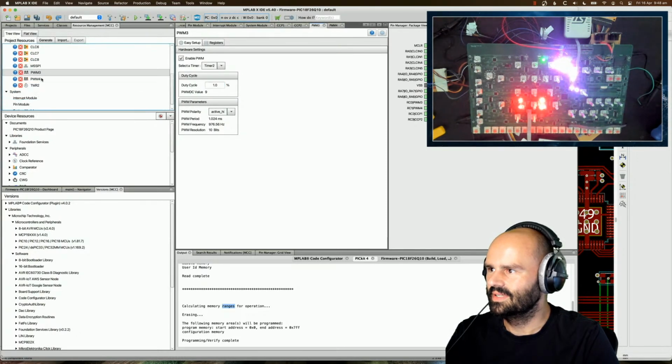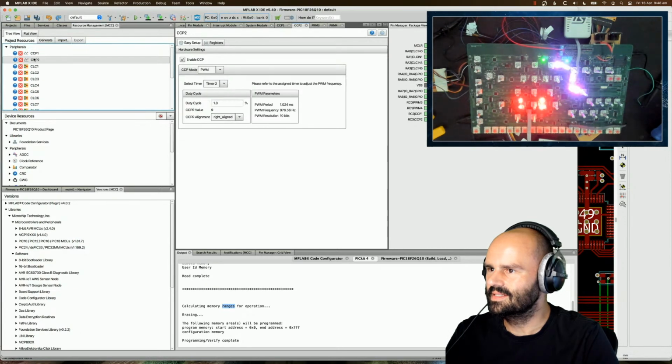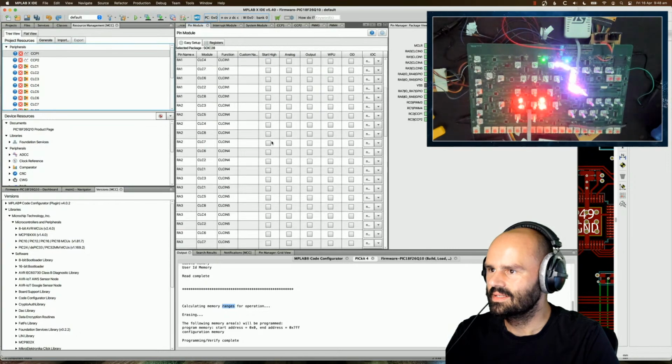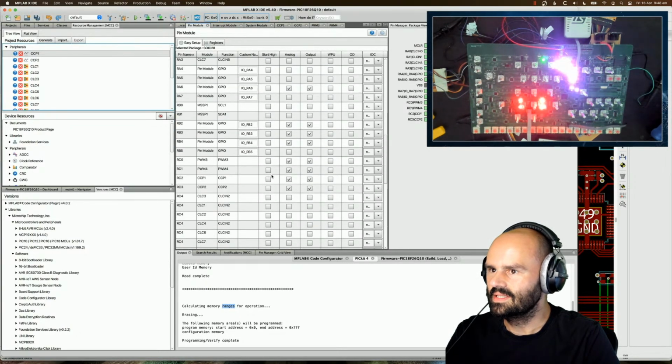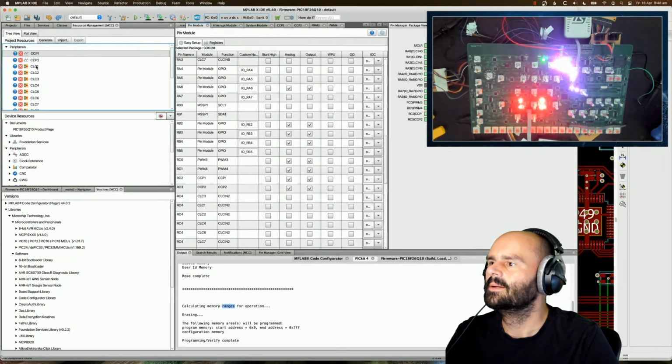So with a duty cycle of 1% and a CCP at 1%, 20%. What's going on here? Maybe we need to check the pins. See what we're doing here. So CCP is configured for analog, it's configured for output. There should be no pull-up or anything else. No, that looks good to me. Likewise, analog and output. Okay, so why is...